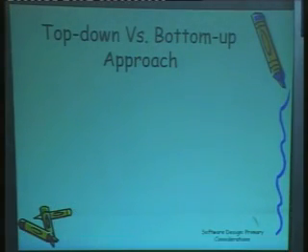One can take a top-down approach to this, or a bottom-up approach. In a top-down approach, you start from a very high-level design description and then break it down further into different sub-designs, subsystems or modules, and go on designing that way. Or you can start from very low-level modules, build them up, put them into packages, and then go on to build the architecture.